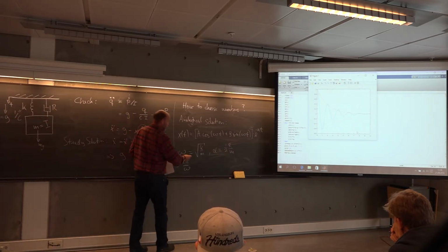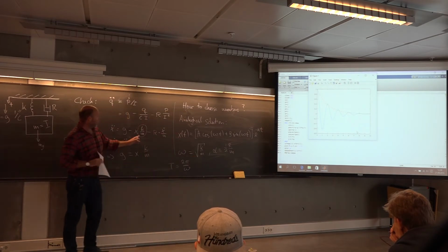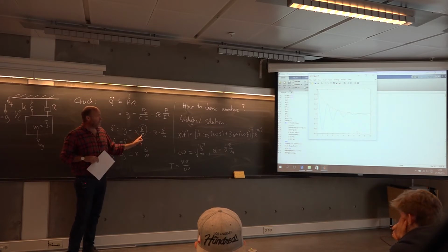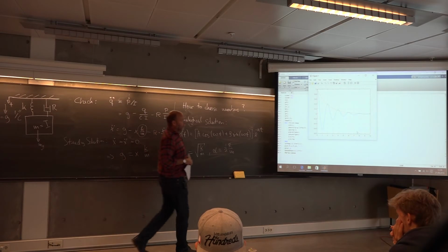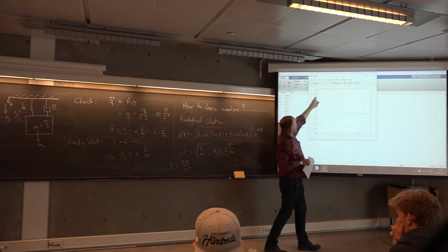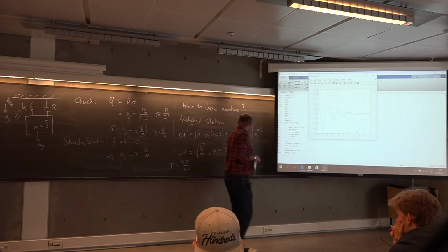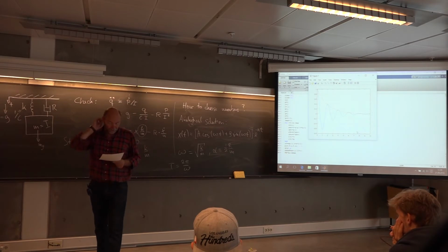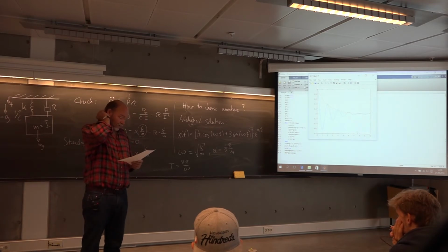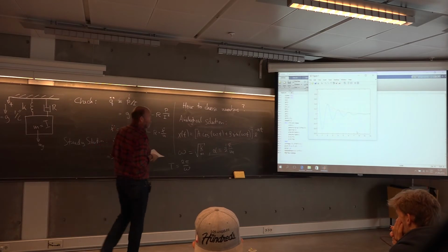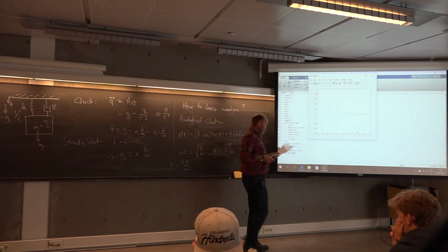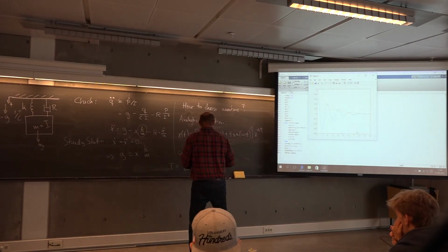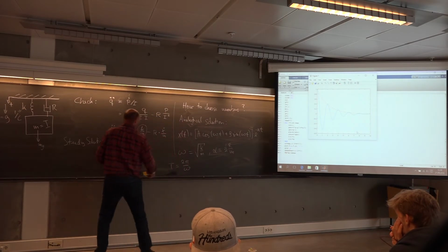So frequency, that one you take from the proportional term here with the spring stiffness, depending on how fast you want him to oscillate. The damping, that will now be a choice for this alpha. So say, for instance, you want this amplitude to drop by 1 over e for one single time period.